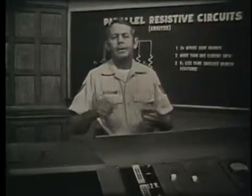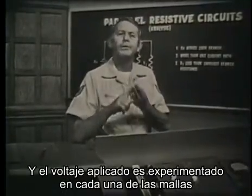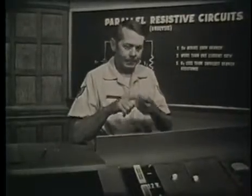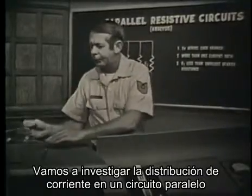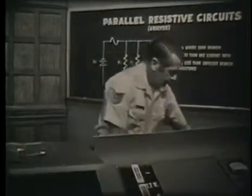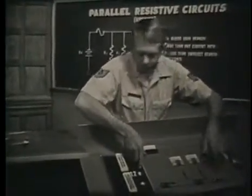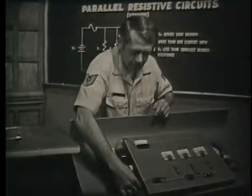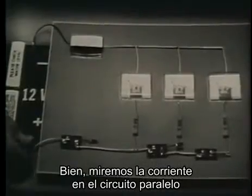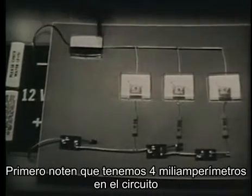All right. A parallel circuit has more than one path for current, and the applied voltage is felt across each branch. Next, let's investigate the current distribution in a parallel circuit. And I'll use another trainer to show this. Making the power connections here. Okay, let's look at the current in a parallel circuit. Notice first that we have 4 milliammeters in the circuit.